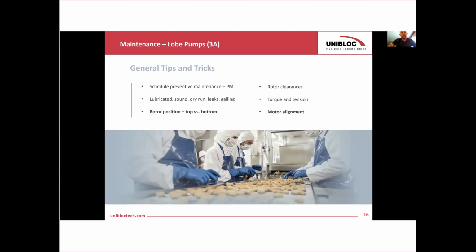If you have small scratches, that means the rotor is touching the housing or the front cover. It can start small, but it can very quickly escalate as well. And the sooner you address that, the better for you. You're going to save the repair cost that way.